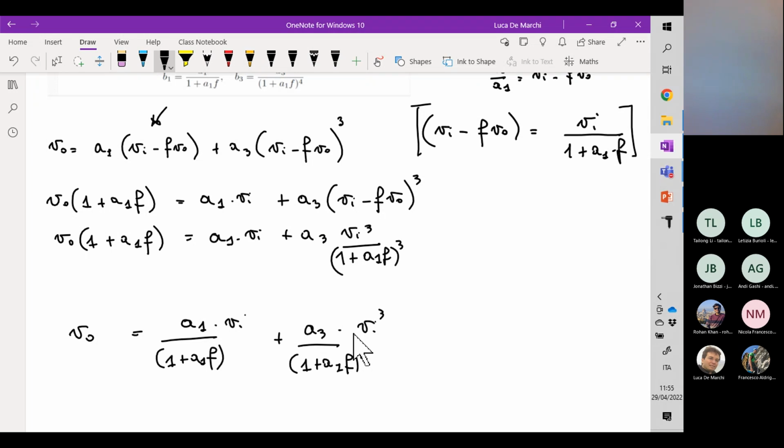So here we have the solid curve here, here, and here. After P1 we start losing 20 dB per decade. After P2 we start losing minus 40 dB per decade. After P3, minus 60 dB per decade.